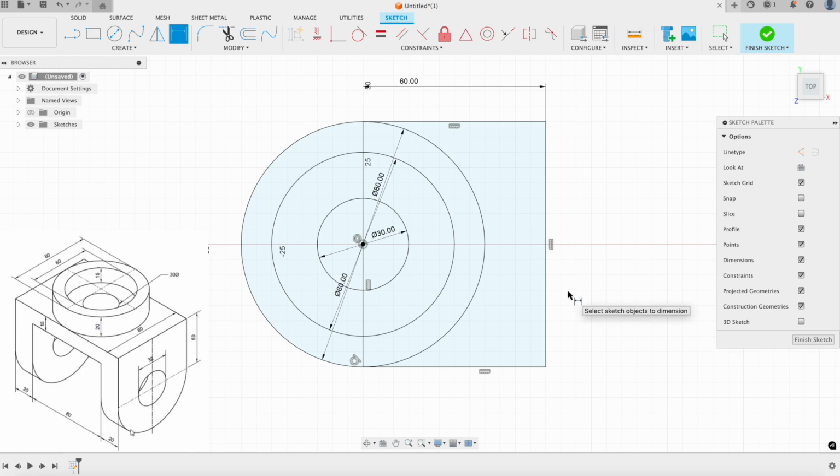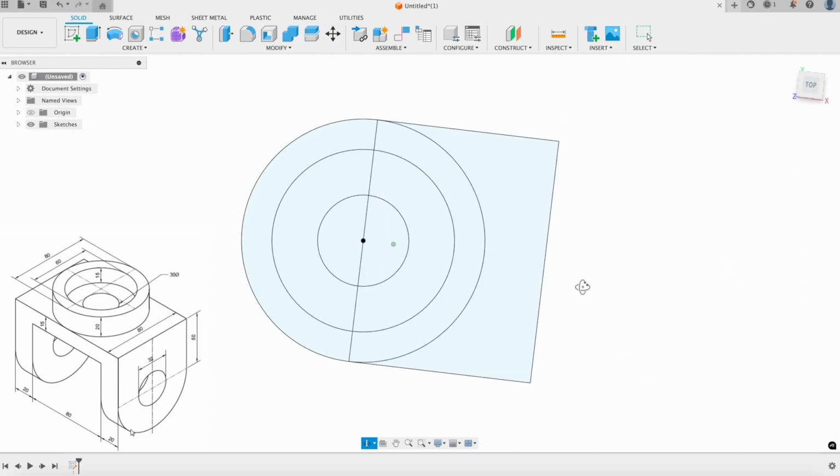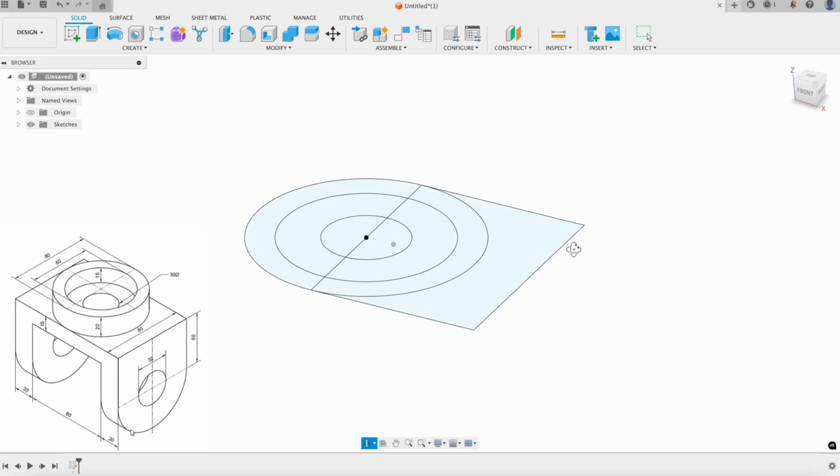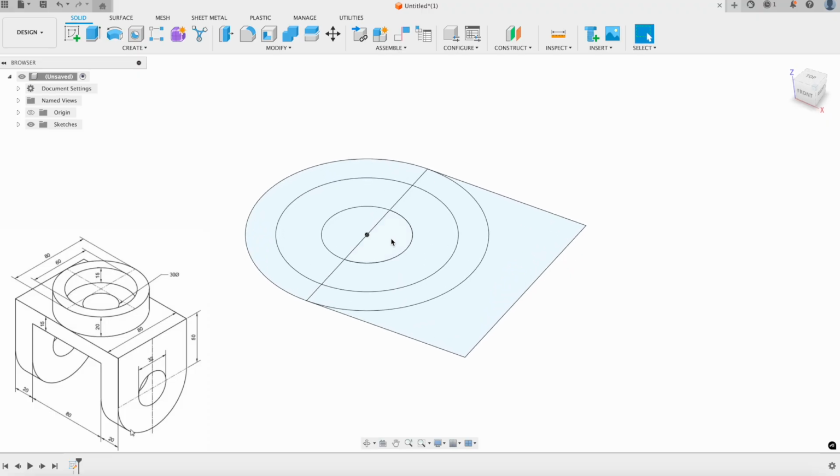Okay, and that is that. So that's all that I can see from the top view right now. So I'm going to go ahead and finish my sketch. Okay, and I'm going to start to extrude this. This center part of the circle is a hole, so I actually don't have to do anything there because I want to keep this as negative geometry, or just empty space. However, I do need to start extruding up this portion of my part and also this portion of my part.